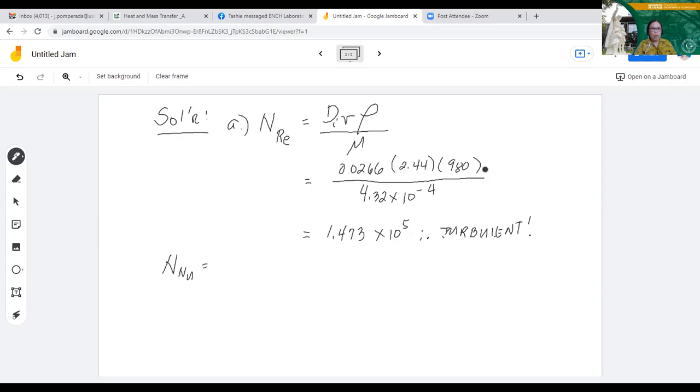And the formula for that is actually hD over k. Now, since h in the original formula for the Nusselt number is hL, this time we'll write it as hi, because the heat transfer coefficient that we're going to consider here is based on the inside part of the pipe where your water is flowing, the fluid that is to be heated.